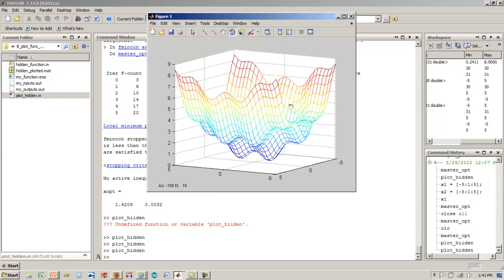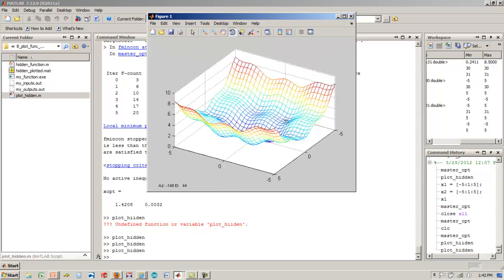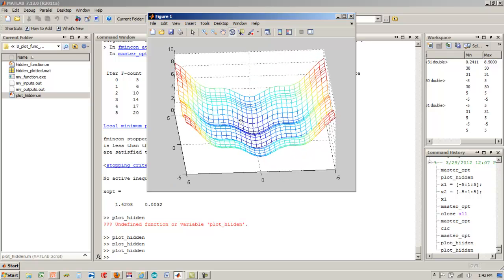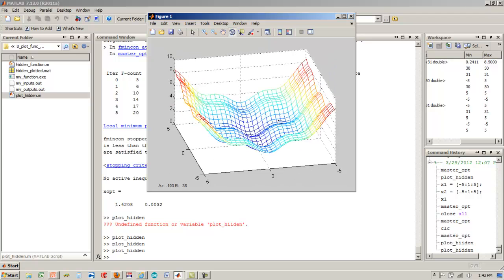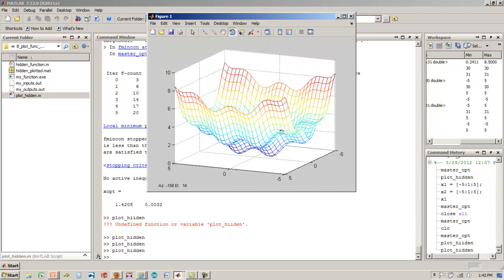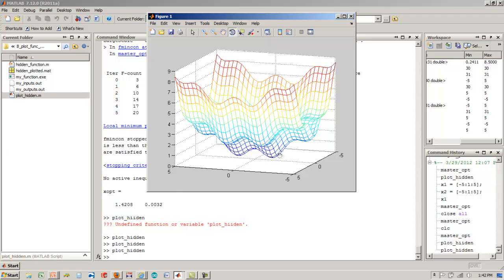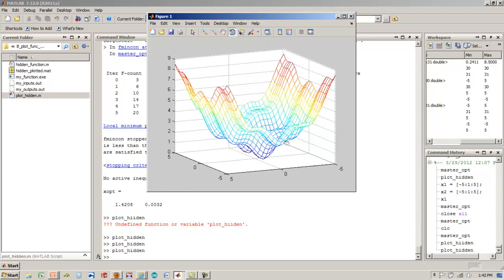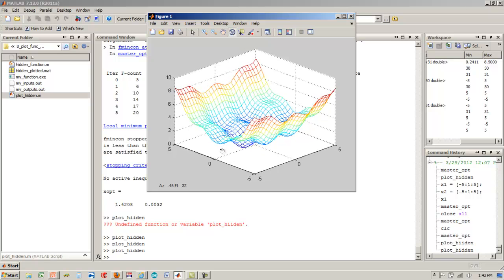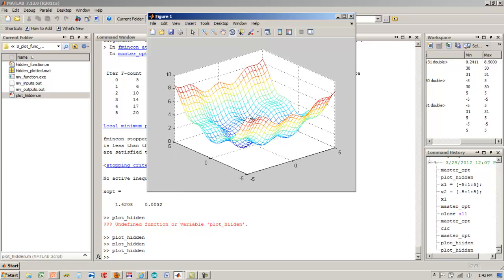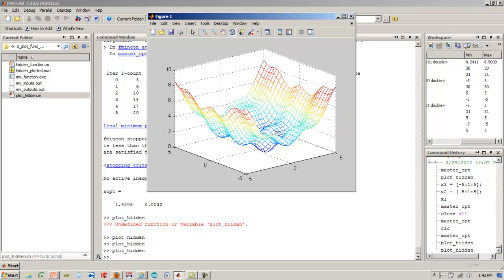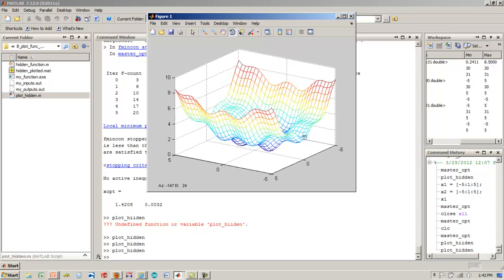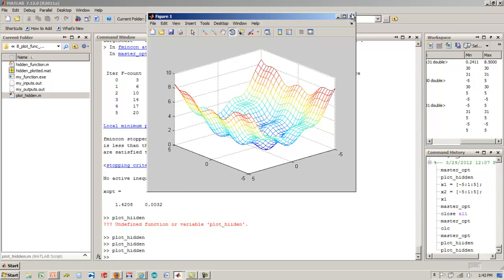And here we have a nice smooth curve, and we can get smoother than this, but after running 30 by 30, that's over 900 times, we have higher and higher certainty that these two locations down here are the global minima, and it's now obvious to us that we have all of these local minima that the optimizer got stuck in, and that's why we had those 7 points in the previous design optimization run.